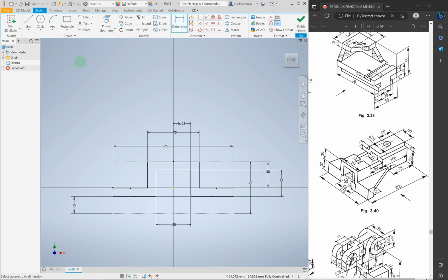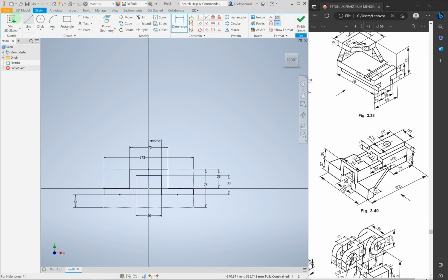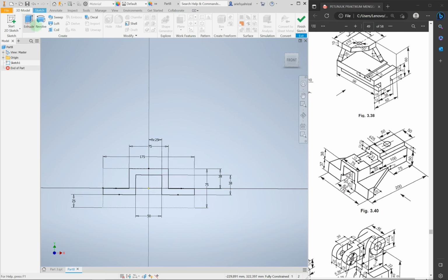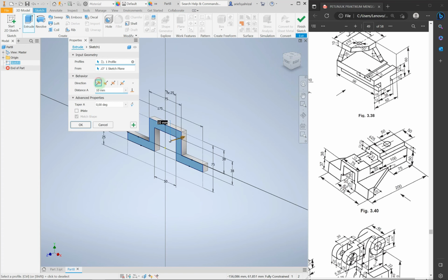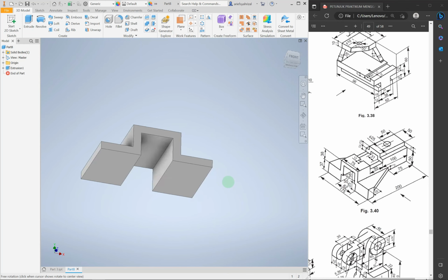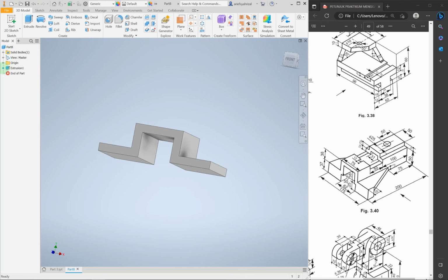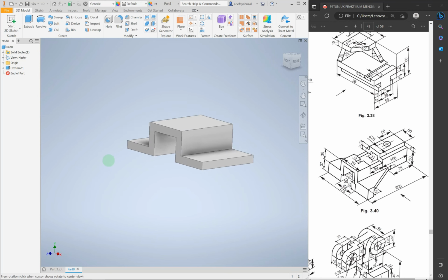And then I'm just going to use 3D model. Go to 3D model and extrude this part right here. I'm just going to select, I guess here. Right there. The distance I'm just going to make to extrude from this surface into this surface. So basically the distance from here to here is 200 minus 100, so basically it's 100. So change the distance to 100 and click OK. So this is it. And maybe we can, yeah, okay, that's okay.